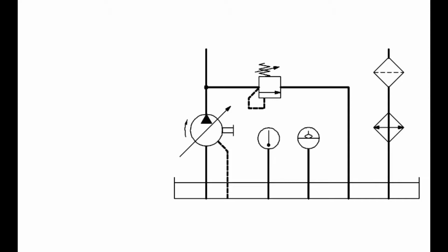The hydraulic pipeline is tapped on the delivery side of the pump, and an adjustable pressure relief valve is installed to control the flow. In the event that the system pressure reaches the preset value, the pressure relief valve opens. The excess flow rate supplied by the pump is then directed through the valve back into the tank.